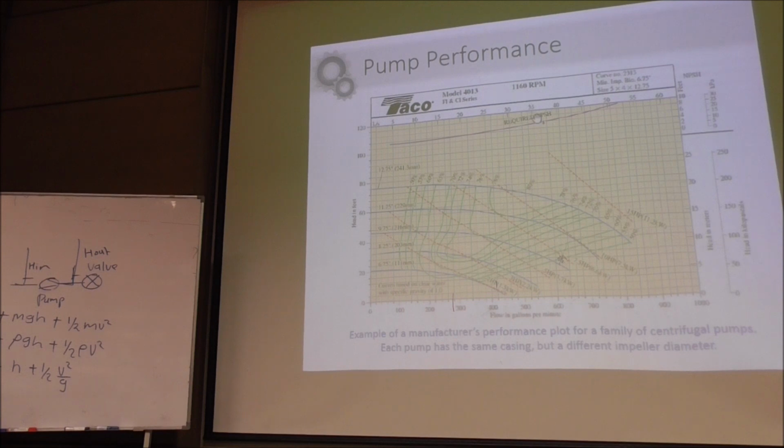One other important thing is, you see up there, you get the required NPSH. This is net positive suction head. This is the head required such that the pump will not experience the so-called cavitation. You remember? If you have a low pressure, water can boil at low temperature, right? We call it cavitation. Cavitation is not good for a pump because it will create the so-called hammering effect. It will explode, and it will chip the blade. Okay, one pop, two pops, it's okay. It's just popping, right? So it's okay. But if you have 1,000 or even millions of it, for a long time, you know it's getting worse, right? Like a torture.